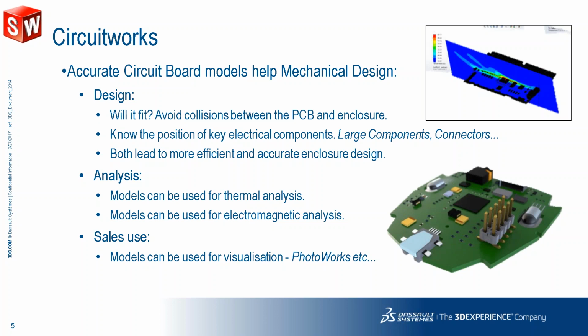While importing, SOLIDWORKS uses the component library, so it can be used with pre-existing component models. It also supports all the IDF files, and in that case you can check the holes, the cutouts, keep-out areas, and check all the notes. The model will also be very useful for thermal analysis and electromagnetic analysis, and of course it could be used by salespeople when you import your circuit boards into SOLIDWORKS to give a visualization of your product.